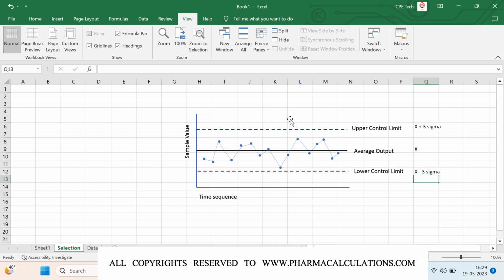Depending upon the data, you will have different types of control charts like the IMR chart, X bar R chart, X bar S chart, P chart, NP chart, etc. So how to do these things and how to select these control charts? Let's take the classification to understand better. Before going into that, we need to understand the different types of data available. Basically we have two types of data: one is discrete and the second one is continuous.